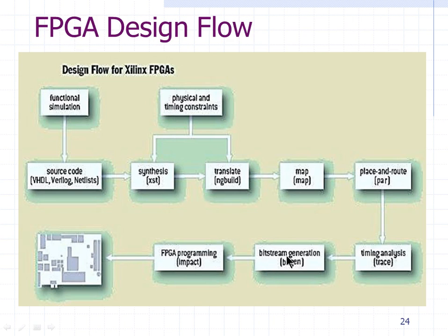The bit file is a file in bit format, or encrypted format, which is the equivalent of the Verilog source code that you have written. The same thing gets converted to a bit file, which is then used to program the FPGA chip on the board. This FPGA chip, once programmed, starts acting like the design that you have written.